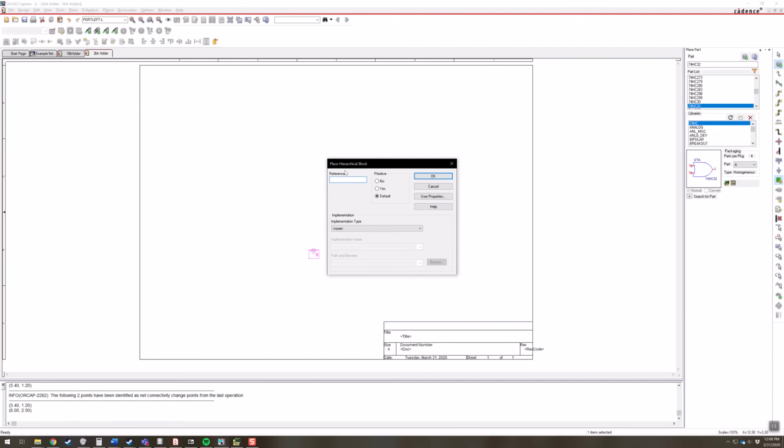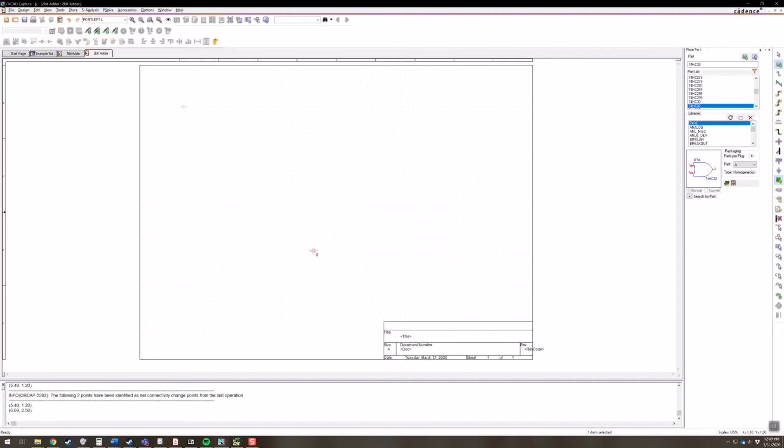So I'll call this 1-bit adder 0, in schematic view. Now if I look at implementation, there are 2 options here now. I'm going to do the 1-bit adder, draw my little box, and so I've got my A, B, C in, sum and C out here.